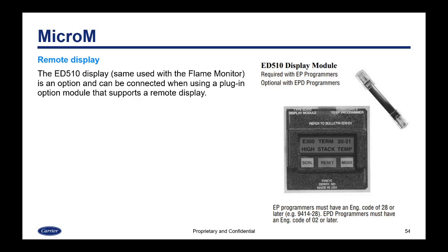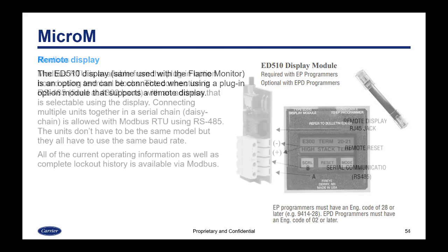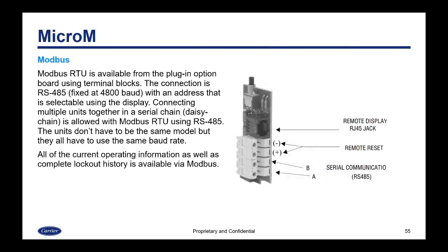Modbus RTU was available from the plug-in option board using terminal blocks. And the connection is RS485 like the flame monitor. Also 4800 baud with an address selectable using the display.